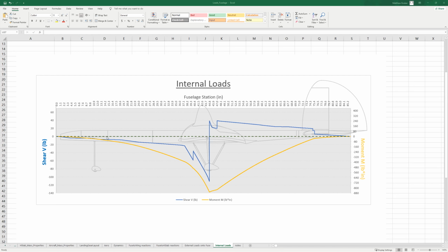But before we did that, this output here is a balanced load diagram. It's the view of sum of F minus MA equals 0 and sum of torques minus I alpha equals 0. So this balances for that one maneuver of the 1.1G flare to 4G impact of the main gear. That would be called a 2-point landing. But we have to check a list of maneuvers that each might be critical for our structure at different areas.